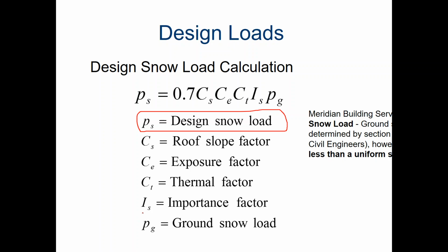Then you have this importance factor. If you have a bunch of people that are in the building and the roof starts failing and it's really difficult to get them out, like in a hospital or something like that, then you need to ramp up the design a little bit and make sure that you're very sure that this roof is going to hold up. And so the importance factor is just going to increase your design snow load by a little bit, as opposed to if you had a building that was just going to be like a driving shed or something where you'd keep some tractors in. That might not have as high of an importance factor.